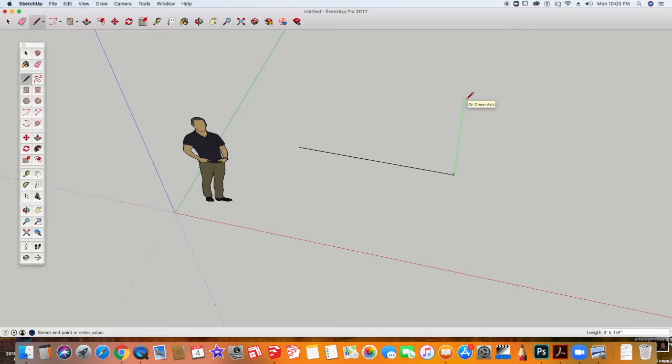it along that, and then I'm going to type into the lower right-hand box there 5 feet 7 inches, which is 5 apostrophe space 7 quotes inches. You'll see that down in the right-hand box, and I'm going to click enter. You can always get away from a tool by clicking escape.